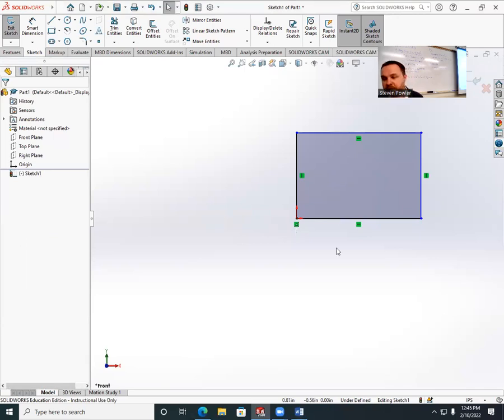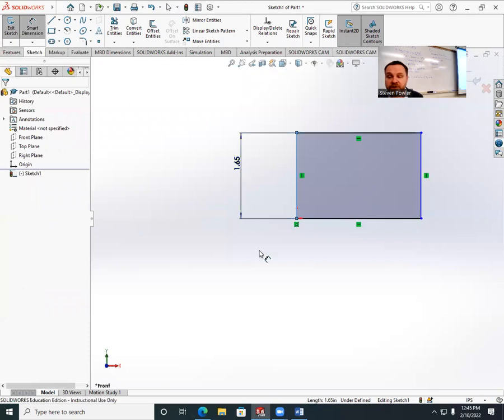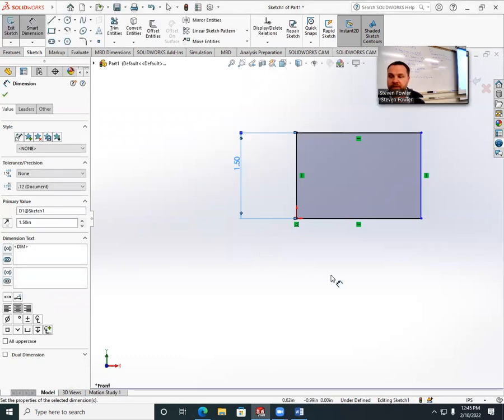That's its location. Now, if I define the size using some smart dimensions, so if I say, well, smart dimension this side, and so again, the way you smart dimension, you select what you want to dimension, or select multiple things you want to dimension between, and then just drop the dimension somewhere out of the way. And I can say, all right, well, let's make this 1.5, and I'm currently in, I think, inches, so 1.5 is okay.